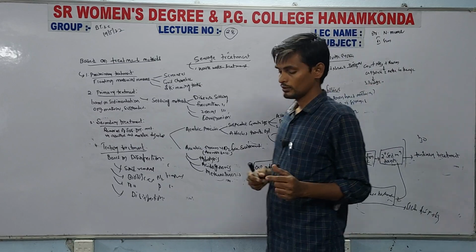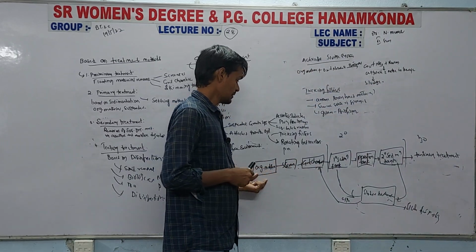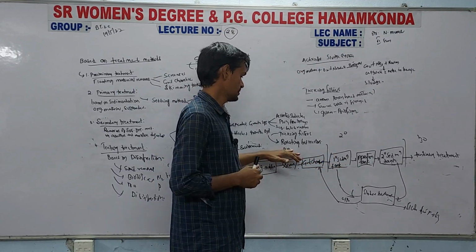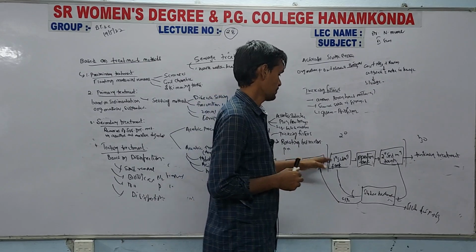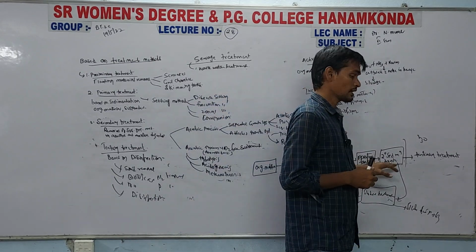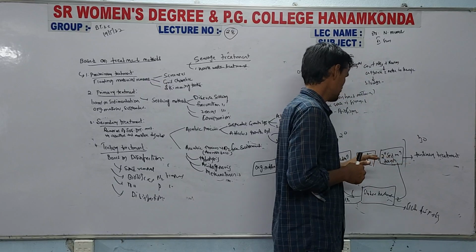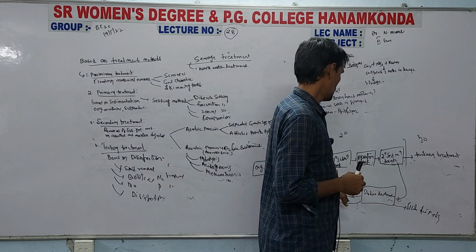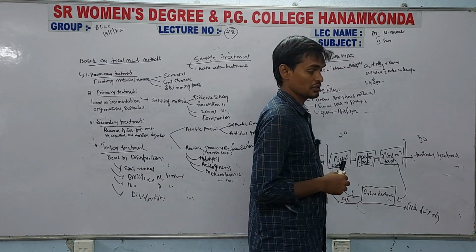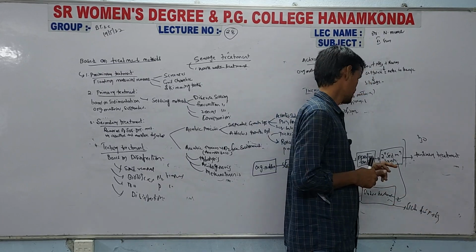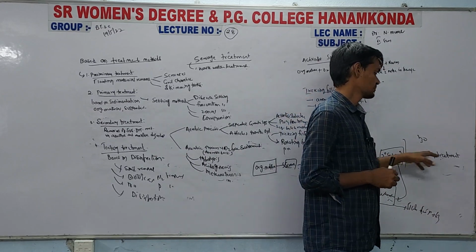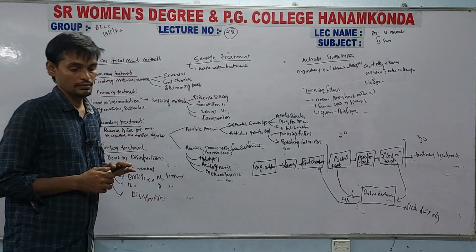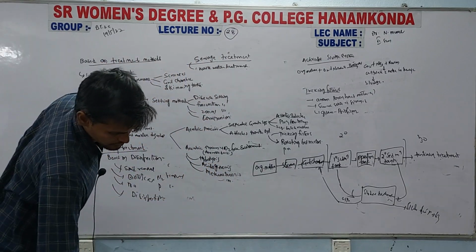If you see the block diagram, the organic matter will be passed over the screeners, grit chambers and primary sedimentation tank, that is called the preliminary method. From the primary sedimentation tank it passes through the aeration tank and secondary sedimentation tank. Whatever sedimented organic material goes for sludge treatment, and the suspension is returned back to the grit chambers and sludge will be disposed, and from there it goes for tertiary treatment. So, this is our picture of sewage treatment. With this we have completed sewage treatment.